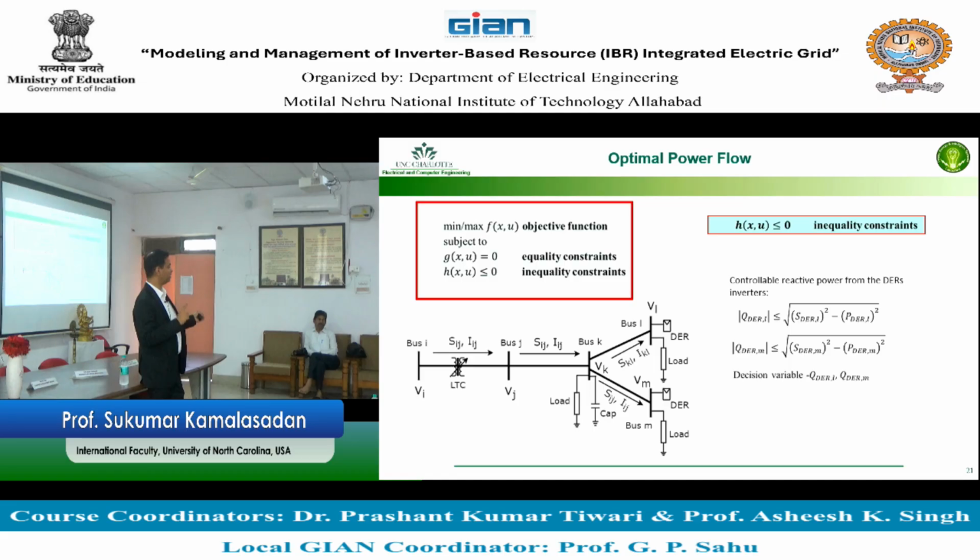So all the PV curtailment that the utilities in the US were doing, they stopped because of this inverter sitting there. They could push all the power, because you have a reactive power buffer. Nobody said that the inverter has to be exactly the same as the photovoltaics. Of course, money-wise, we want to make it safe, but it's economy of scale, right?